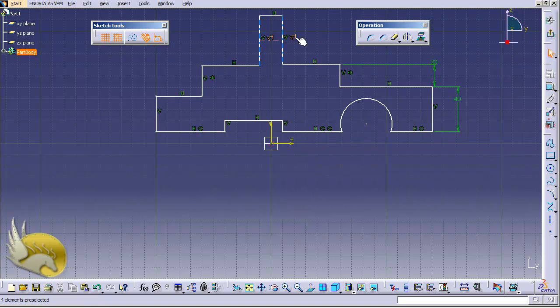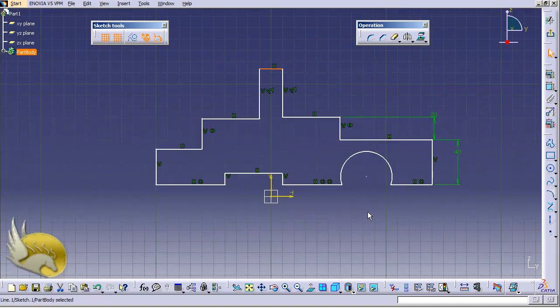You can see that these have some shapes like this. Okay, now I want to click on this. Let me press the control button and the down arrow key once. By selecting this top line and adding a constraint of length, you can see that two of my lines turn green. This means that these two lines are fully defined. They do not need any extra constraint.